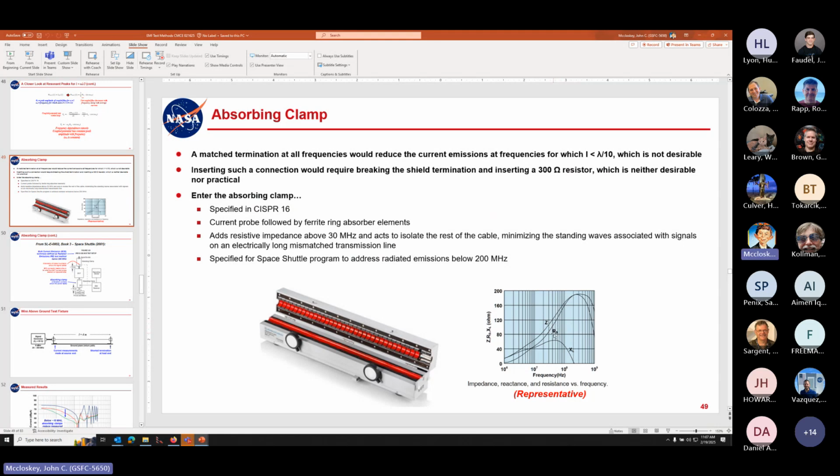That's where it's doing more of the damping or absorbing. That's where it's absorbing or damping out those peaks. So down here in the lower frequency range, you're in the more inductive part. I mean, they're ferrite beads. They're going to be inductive.